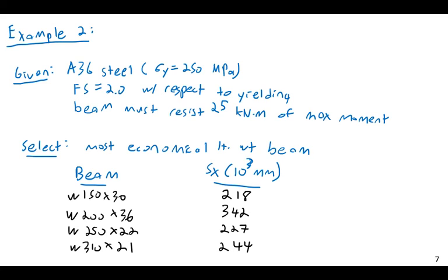That's a construction nightmare. There's a high probability that somebody's going to put the wrong beam in some place, and then something's not going to fit, or something's going to be overloaded. Also it's going to be a lot more expensive, because the more you order of something, the cheaper it is per foot. So often it behooves you on a large project to say, you know what, we have a contract with a steel provider.